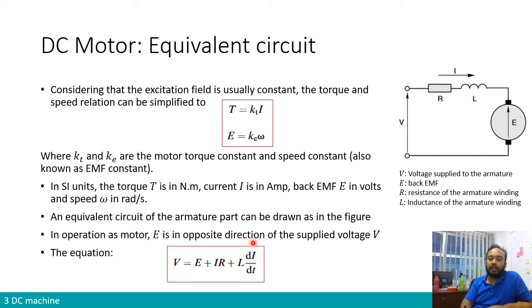So if we look into this equivalent circuit, we can basically write an equation that relates all the parameters using your Kirchhoff voltage law, right? So you will end up with having this equation. Okay, so if we're going to show step by step. So you have the voltage V in this direction, you have the current circulating inside the circuit in this direction, therefore you have the voltage across the resistance over here. So this is the voltage across the resistance, which equals I multiplied by R, right?